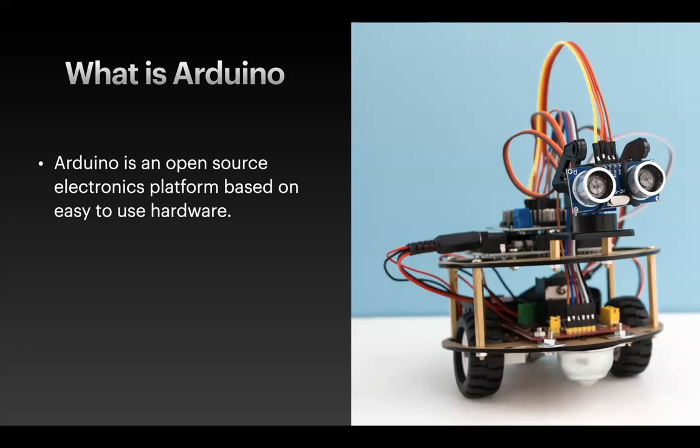Right. So then again, Dilith Karuna Tilaka is asking me a question. How do we provide power to the Arduino without using a computer or Arduino cable? Right. So there is a port in the Arduino board which we can provide 5 volts, right? And exactly, we will learn how to power up an Arduino using this 5 volts, without connecting it to the computer, right?